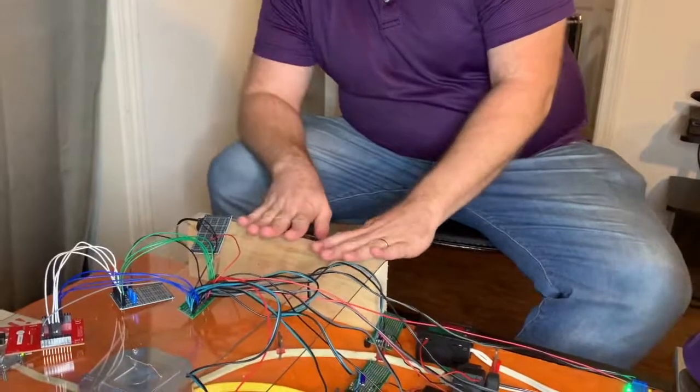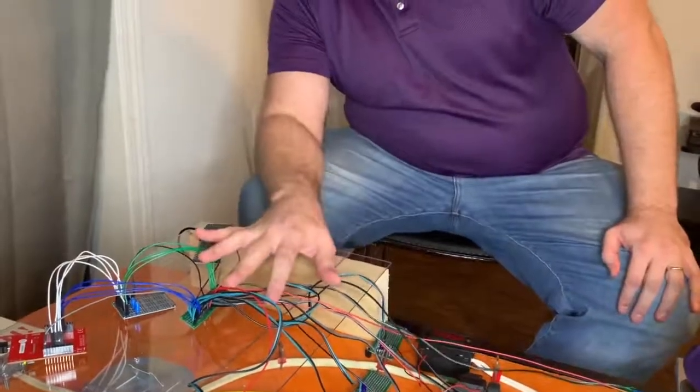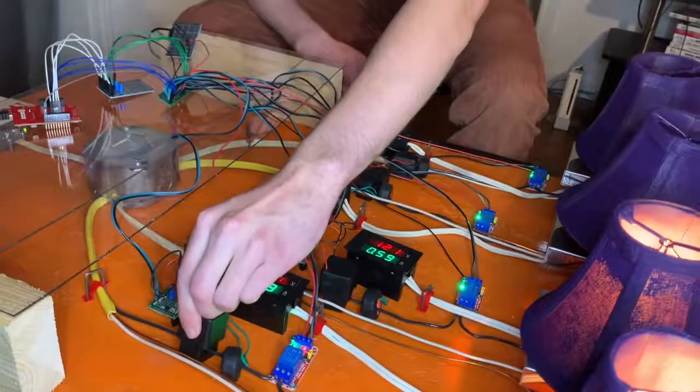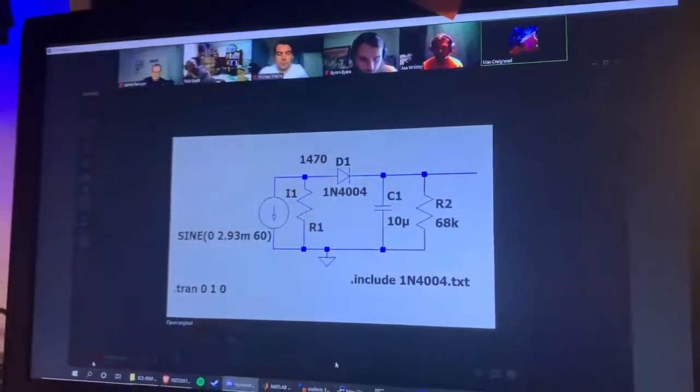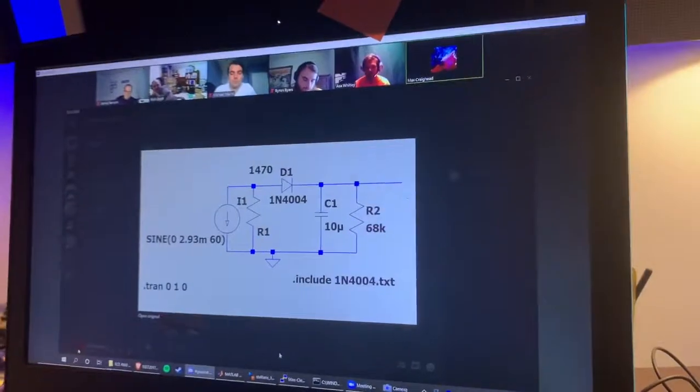The system wound up having 4 subsystems. The first was the current transformers and the circuitry that goes along with them, as well as the actual voltmeters and ammeters that we attached to each line. The current transformers themselves use a 1,000 to 1 ratio, which means if 1,000 amps are going through the line, hopefully not, then 1 amp will be output from that current transformer. Those transformers are attached to a low-pass, full rectifying circuit, which creates the voltage signal that goes into the TIVA, and that leads us to the second subsystem, which is the knapsack solver.